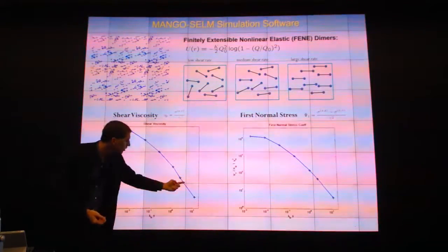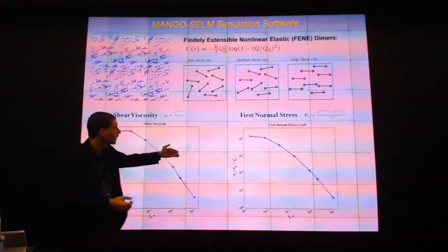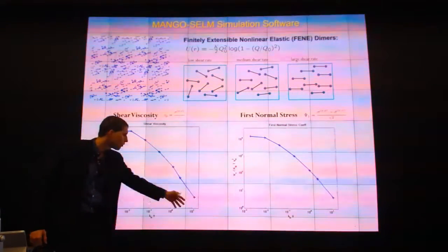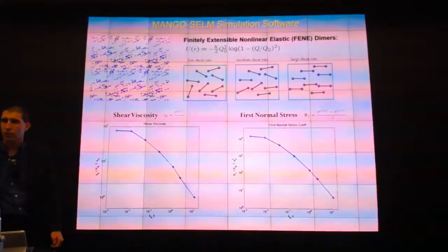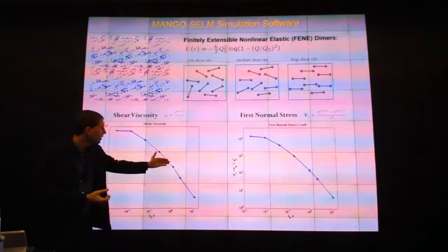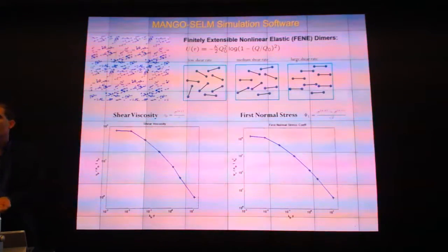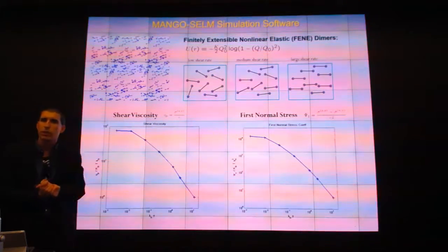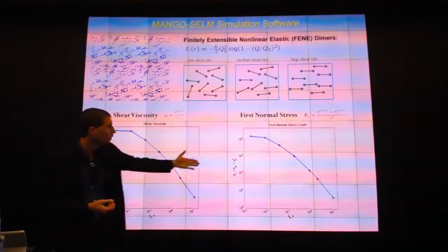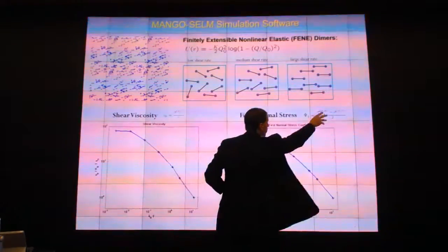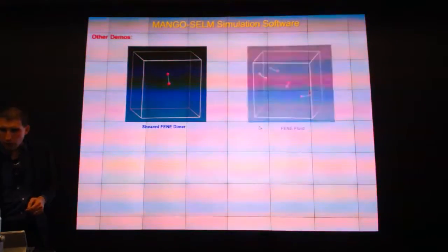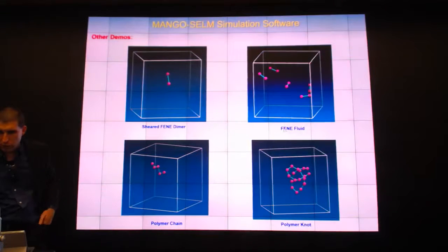And so you get the so-called shear thinning behavior, and eventually these things will all be perfectly aligned with a negligible perturbation, and you'll essentially have a negligible contribution to the shear viscosity. That's known as shear thinning, because the more rapidly you shear the fluid, in some sense, the less viscous it responds, which is maybe similar to the type of response you would have expected if you had less concentration of your polymer. Okay, and then you can also look at the normal stresses, which are just the other two components of the stress tensor.